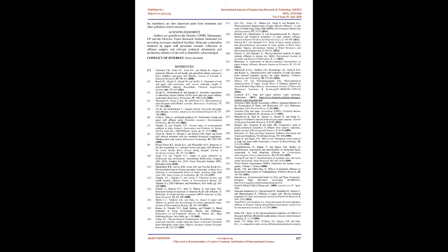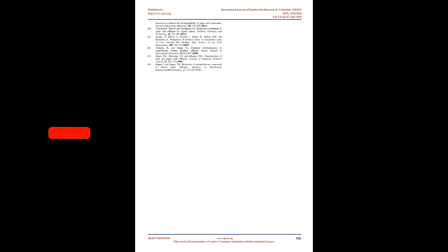9. Determination of AOX. The bleaching sections of paper mills generally use chlorine-based chemicals which result in release of organically bound chlorine compounds such as dioxins and furans, chlorinated phenolic compounds, etc. in the effluents discharged from these units. The adsorbable organic halide, AOX, is the measure of such organically bound chlorine compounds.